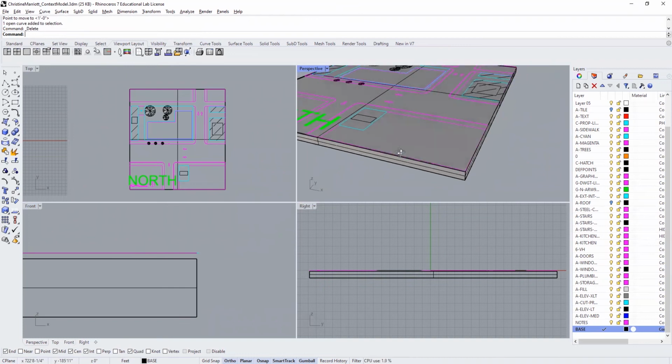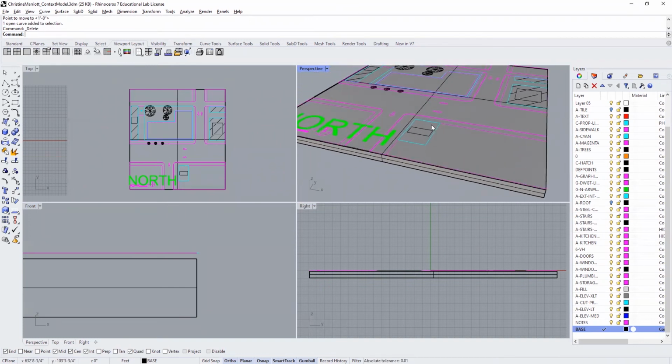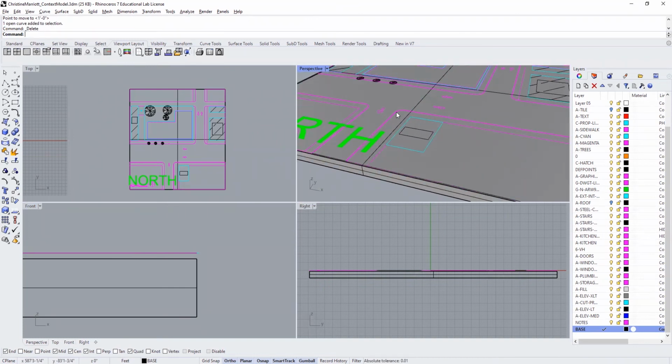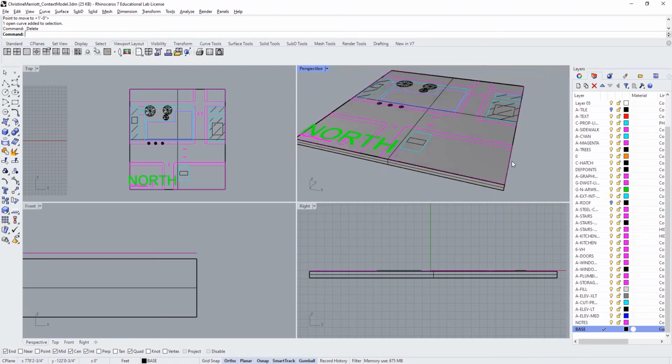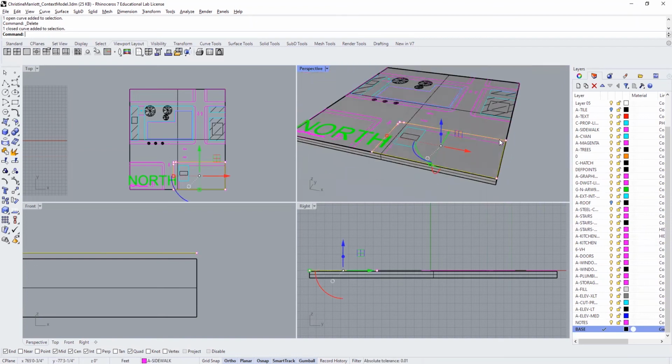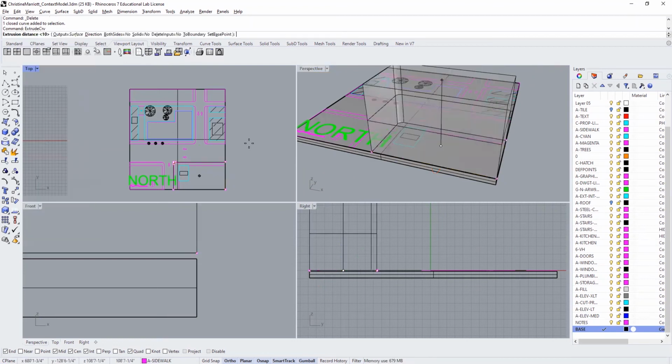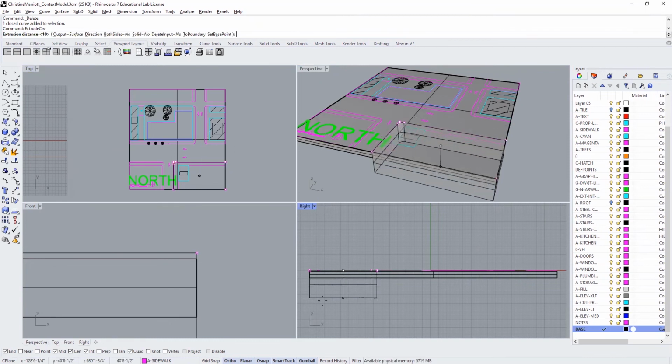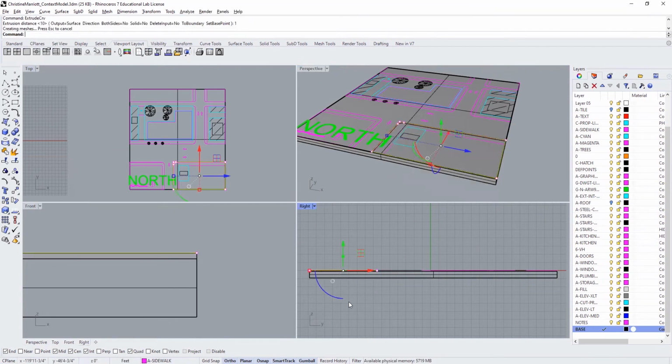All right, so next step is to create 3-dimensional forms out of these areas defined by the curves, not curve with a V, but curve with a B. So I will be picking those polylines that I had created in AutoCAD, and I will use the extrude curve command to bring it down 1 foot, confirm the point, right?